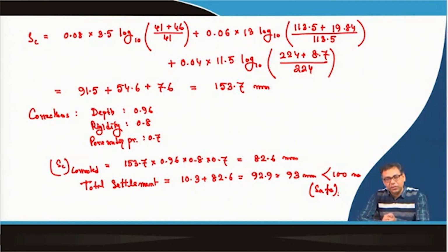But suppose you are doing a rectangular or square raft or a circular raft, then in those cases you have to use the plate on elastic foundation. That concept I have given with the beams on elastic foundation, and it is a similar concept, so you can use it for the plate and analyze. Because the scope of this course is to introduce soil foundation interaction, it is not a total course on soil foundation interaction.